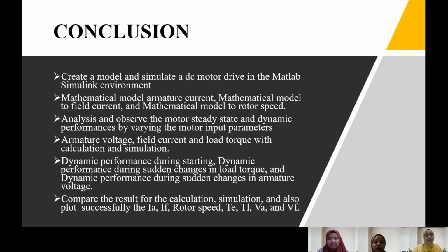Thank you, Shakira. Okay, for the conclusion, students are able to create a model and simulate a DC motor drive in a simulating environment, which consists of the mathematical model of armature current, the mathematical model of field current, and the mathematical model of rotor speed.